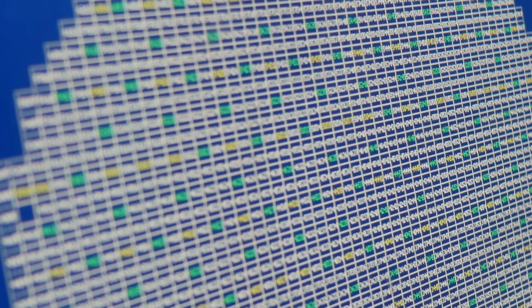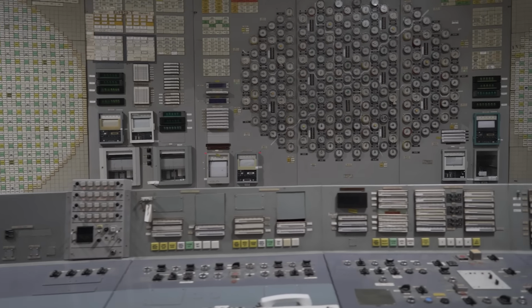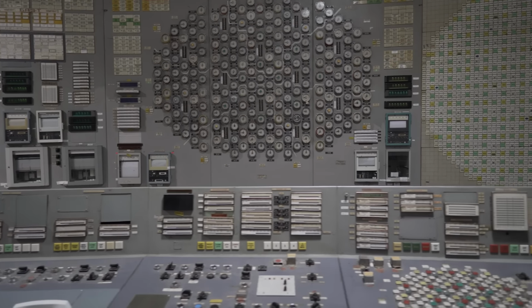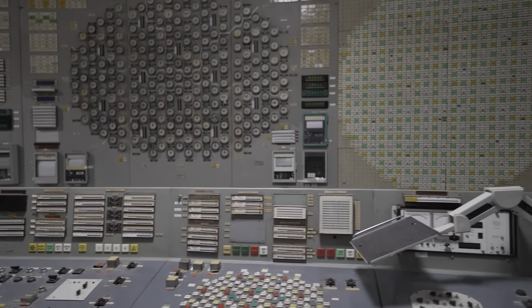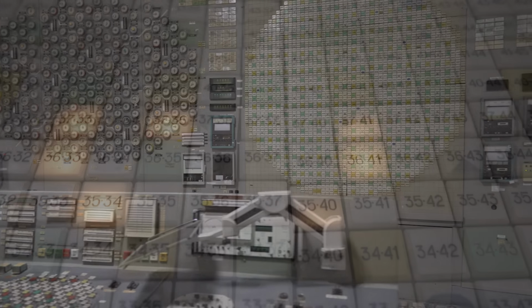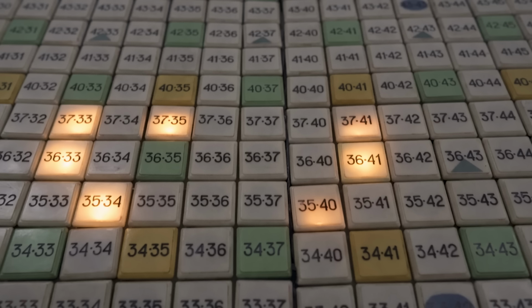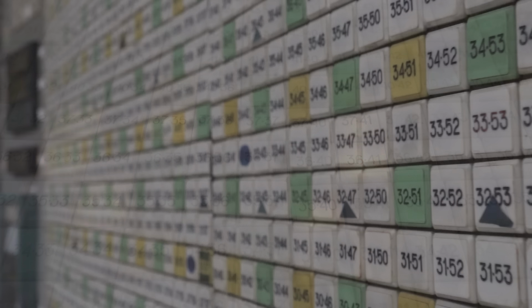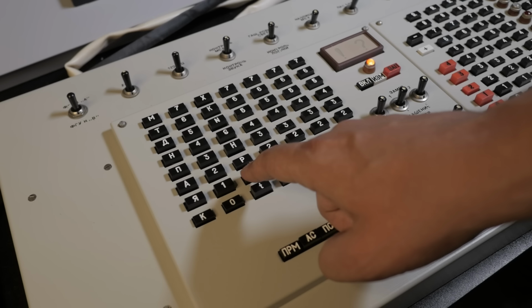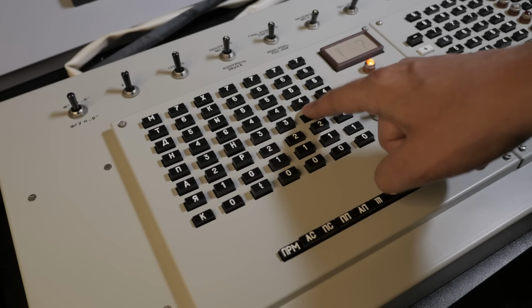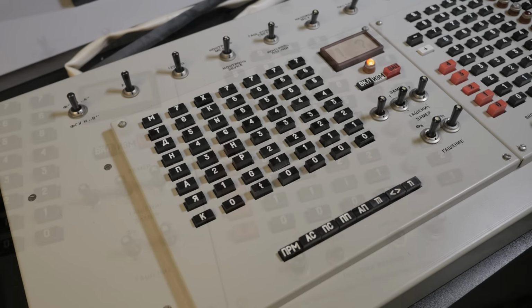And here we come to our fresh upgrade. A few details if you are here for the first time. These round displays are called mnemonic displays of the reactor channels, or MTKs. And their function comes from their name. Put simply, on them light up the marks of the reactor's channels which match a chosen condition. And on each square there are written coordinates of the corresponding channel, so the operator can visually assess the situation inside the core. Then, if they need, using those coordinates, they can type here a request to see more information.